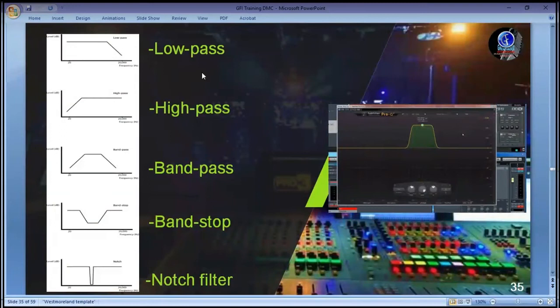So you use the high pass and you block all your low. It means that some frequency will not come out from your top. Then for your sub, which is the woofer, you use the low pass. You allow some frequency to pass at low, then when it gets to where you want to cut it, you cut. You roll it off, so some frequency will not go into that low end.